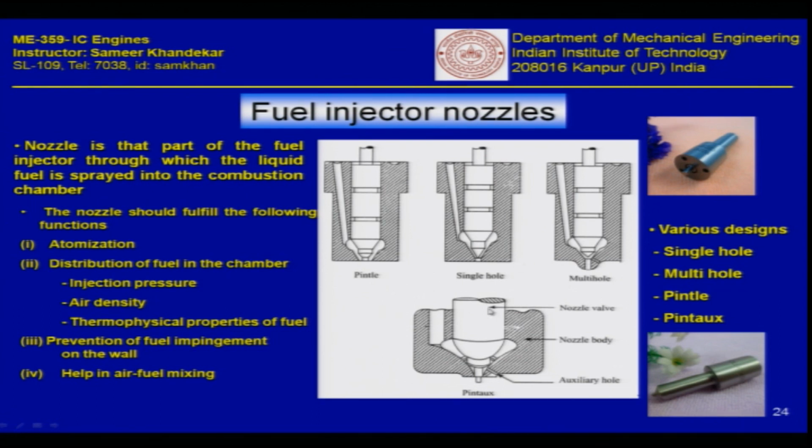Even with a very large excess air ratio, or a very lean type of burning, even if you supply a very large quantity of air, still you find smoke coming out of diesel engines, at high power especially. That is because if the spray characteristics are not good, if the turbulence and mixing is not proper, then within the time available for complete combustion, you may not get the actual burning efficiency to be high enough, and therefore, before the exhaust valve opens, you already have some unburnt fuel or carbon deposits or smoke, and this smoke comes out of the diesel engine.